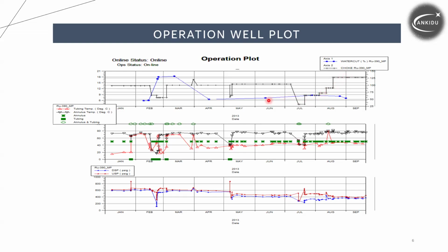Why? Because the data suggests we need to choke back the well, because here you can see the well is not flowing perfectly. Maybe it's related to the tar, when we have tar and then it's opened again. Is it stable enough? We can see the temperature and pressure for the upstream and downstream are just not like before. It's now September. This is in March and April, so it's going down and going down. Maybe that can be an indication that we have a rising water cut.